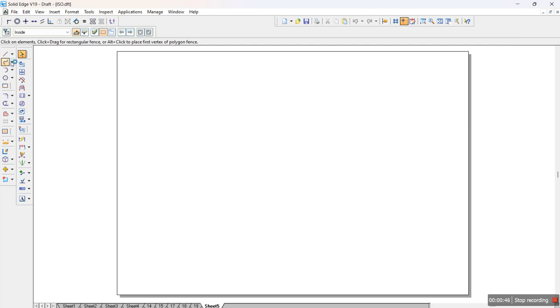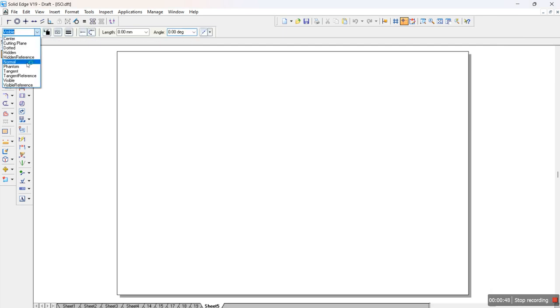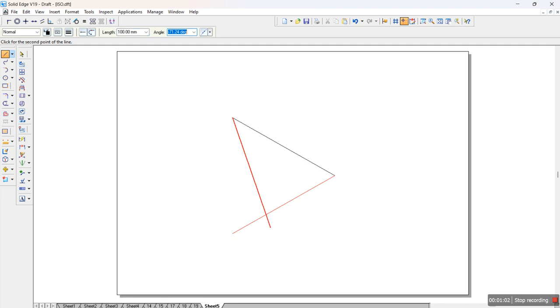So let's start with the software. We'll take the line as normal. Cylindrical slab is of 100 mm, so we'll draw an isometric square of 100, 100, enter 30, again 100, enter, angle as 150, 100, minus 150, 100, minus 30.